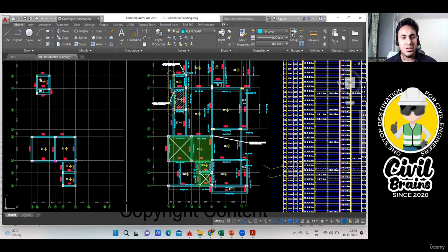Agree with me? This is that area which is shown, and this is that area which is shown. In the same way, this much area is shown here. That means definitely this much area is shown there. So now when I calculate the columns, not all my columns are going. All these columns you can see here, none of them are going to the terrace level. Only these columns that you have here and these columns that you have are going to the terrace level. So I need to pick only those columns and write them in my Excel sheet.